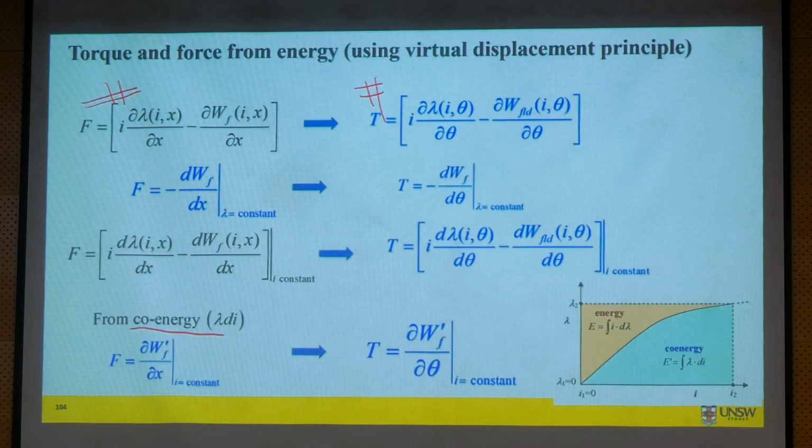But in the finite element method, once you know the flux linkage, this stored energy can come from, let's say, inductance. So this will be your half L i squared. If we know the inductance, this energy can be estimated. This is simply half L i squared, the magnetic energy stored in the inductance. So they try to solve this equation numerically and give us either force or torque, as we did.